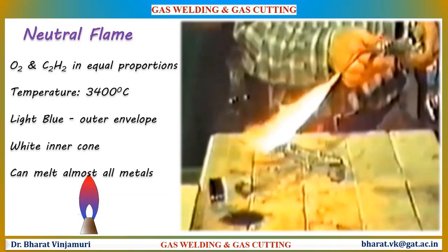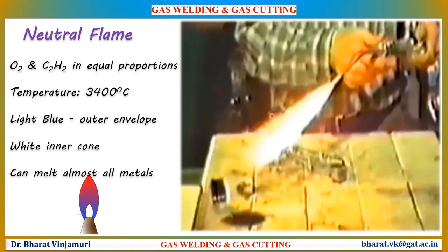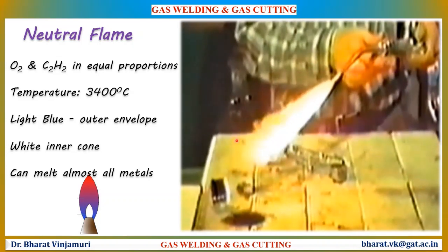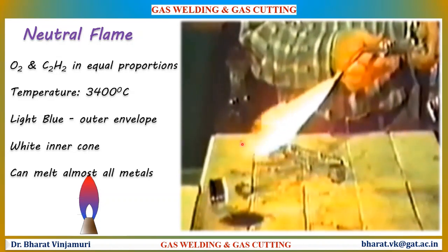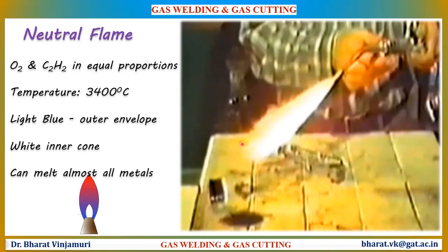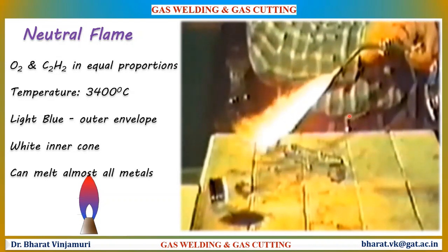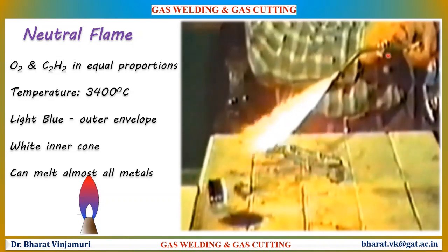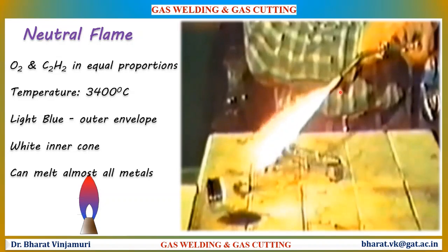Open the acetylene valve slowly until the smoke at the tip of the flame reduces. Once the smoke has been reduced, now you can open the oxygen valve in the torch slowly and notice that there is a bright flame that settles in a different color.